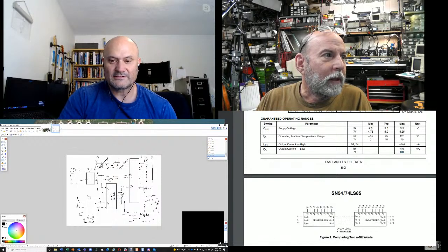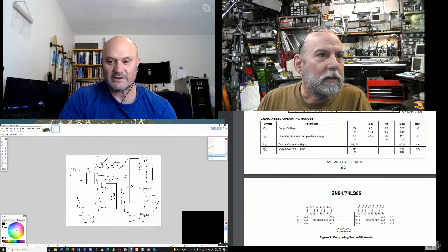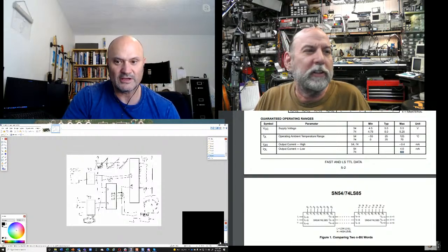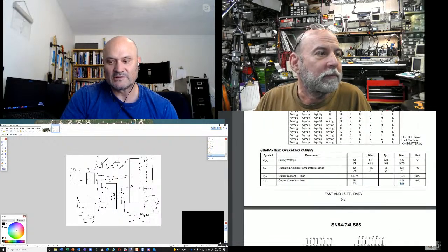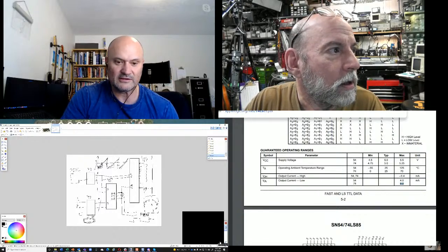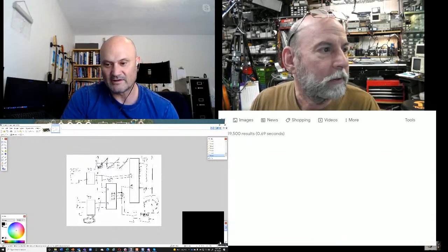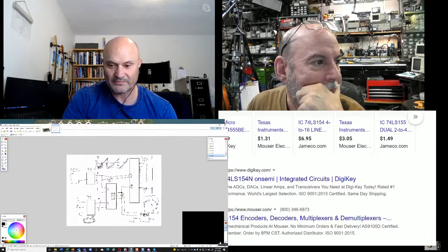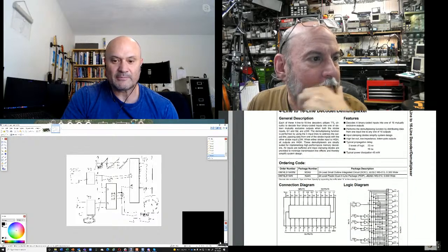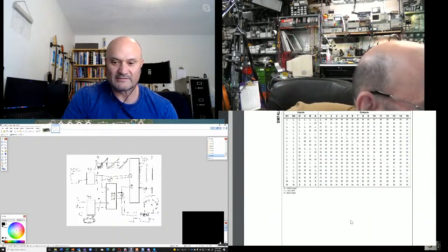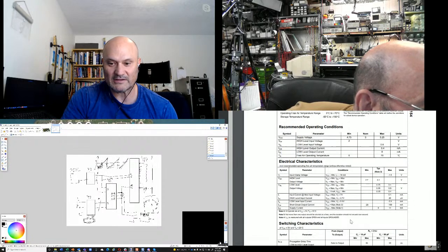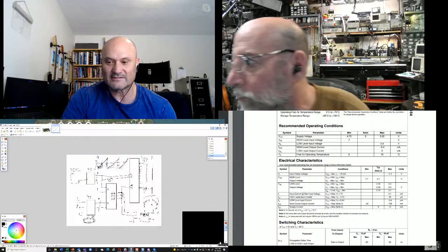Yes. LEDs usually have a maximum rated current of 20, sometimes 30 nowadays for the super bright ones. Back then they weren't very efficient. But usually a standard rated current for an LED was 20, but you can drive them with less. So you choose the appropriate one. I had like a 1K resistor. And sometimes those things in the data sheet are very pessimistic as well. Sometimes you can actually push them way past, but this is recommended conditions rather than maximum.